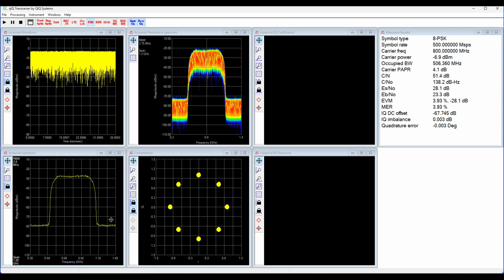We've lost more than 20 dB of dynamic range in the system as we've gone through this demod. And it's not due to thermal noise. The thermal noise floor is right here. This EVM is being caused not by noise, but in this case by other components in the system.